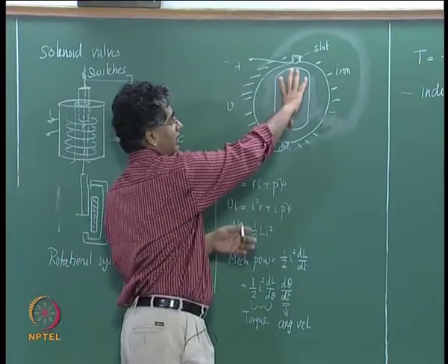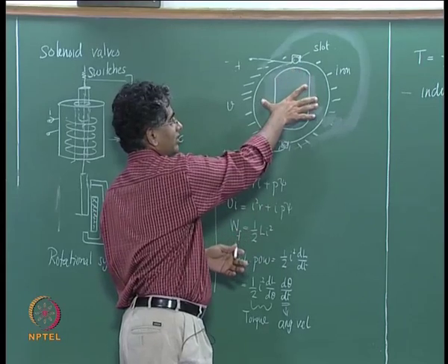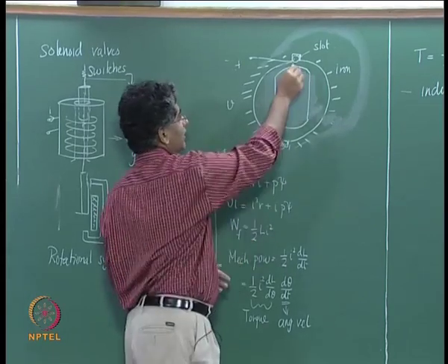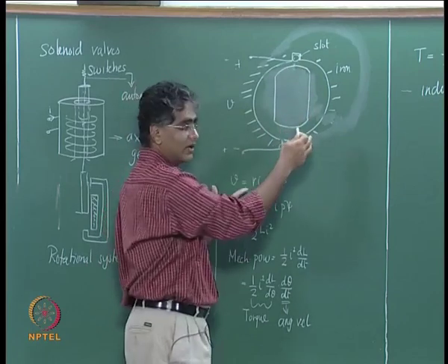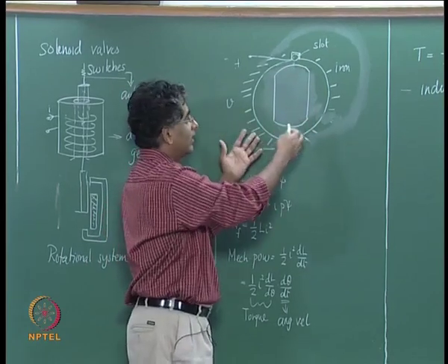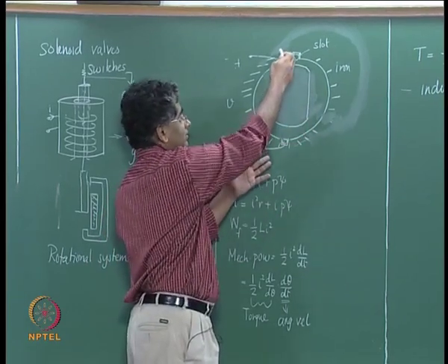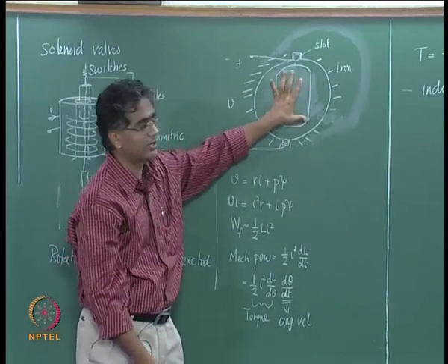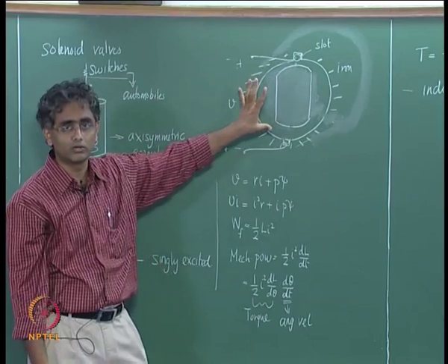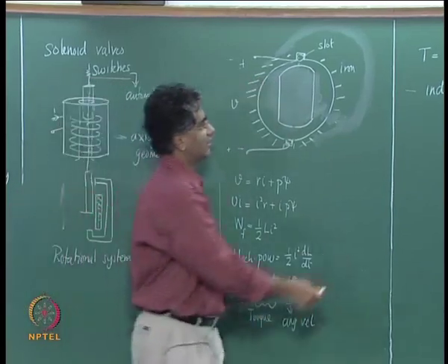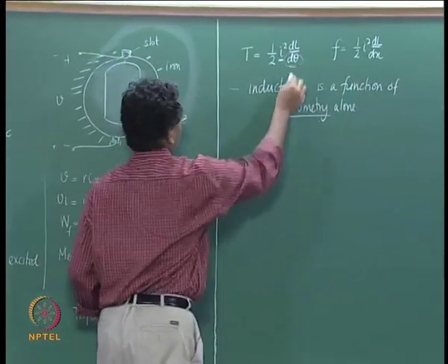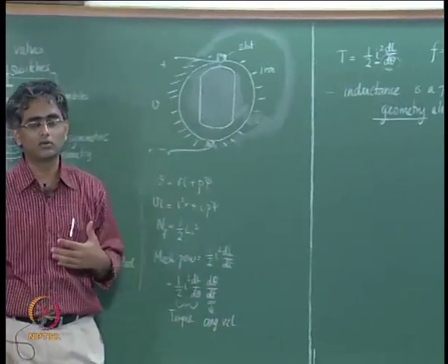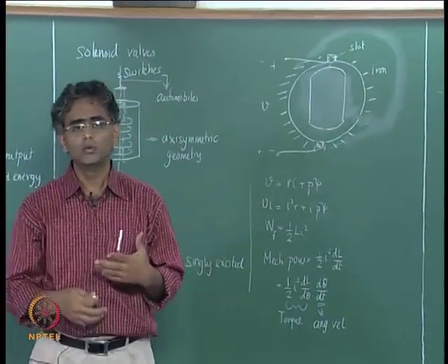Whether the rotor is here or whether the rotor is here, the air gap that is there at a given angle is completely different, and therefore the inductance that this coil would experience is different for different angular locations of the rotor, and therefore there is some value for dl by d theta, and in this case therefore the rotor will definitely move.